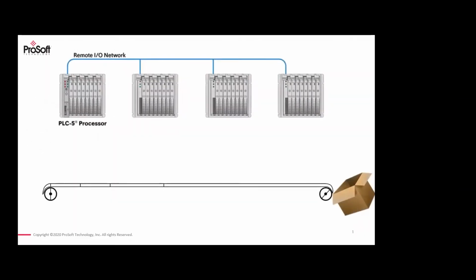Now, to get the point of productivity across, let's look at a numbers example. Say you have a remote I/O network connecting a legacy PLC to legacy I/O at a bottling factory. The controller is responsible for bottle capping. Say you have a bottle spacing of 2 meters and the average real latency of 500 milliseconds.